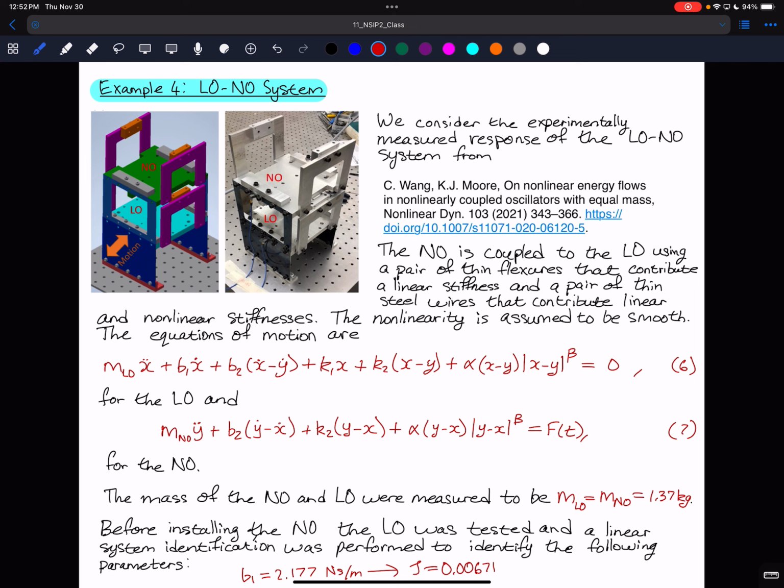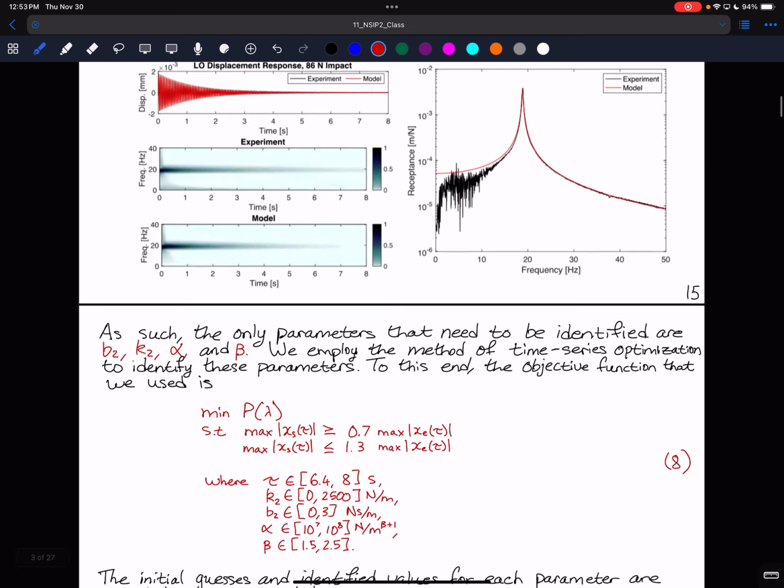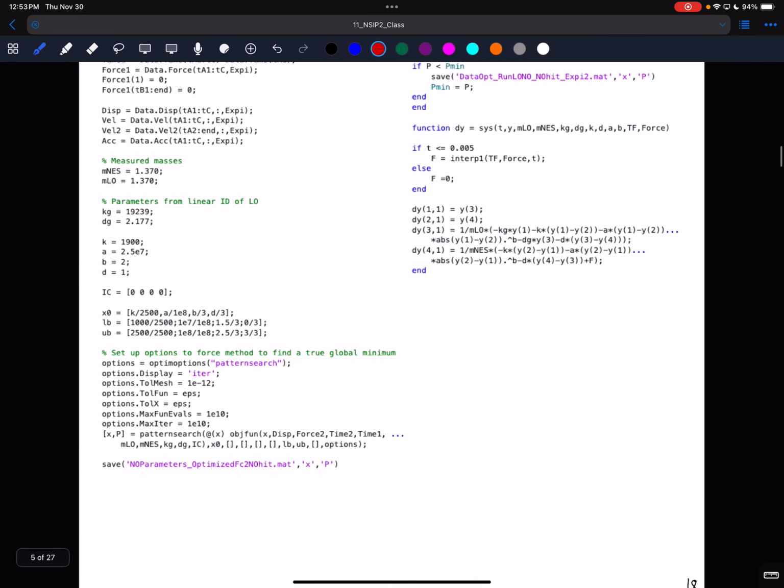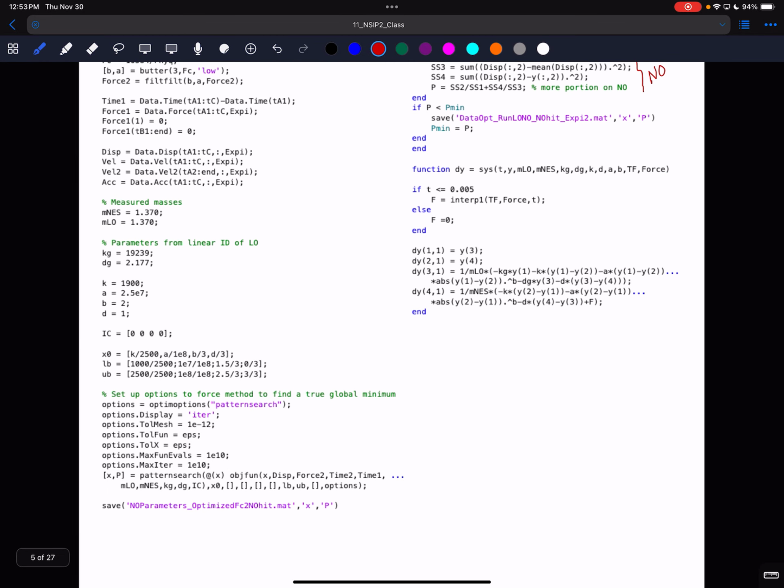Generally, one thing you can do, although you run a risk with this, is run the optimization without those extreme optional parameters being set, find a local minimum, and then try turning this on using that local minimum as an initial point. You may or may not be able to find a better point. It depends. Generally, I try different initial conditions and see what happens. And another thing I do, even after applying these extreme constraints, is once it's converged, I toss the solution it found back in as the initial conditions and make sure that it truly converged.